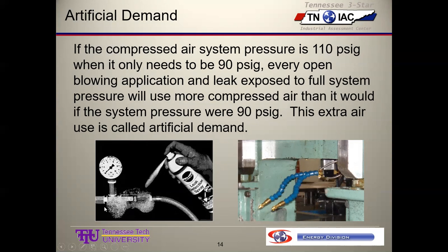And this is a leak. This is a leak detection spray. It's like soapy water, and you spray on it. And if there's air coming out, then it bubbles up. That's one way to find them.